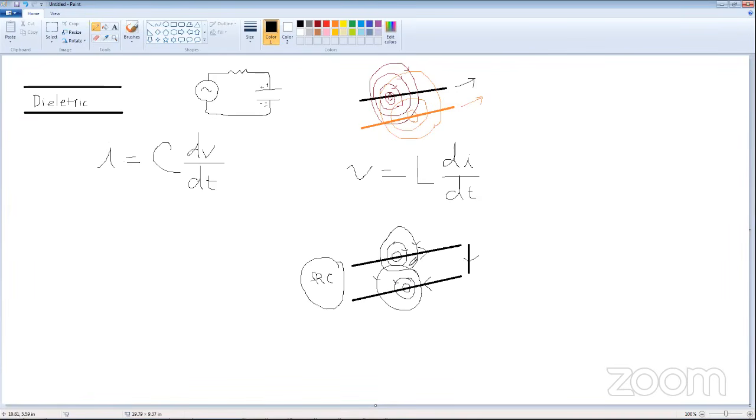So they end up canceling, minimizing their impedance. What this means is that on a PCB, even if you have a huge ground plane, the return current is going to try to follow the signal current as closely as it can, because in doing so it's going through the minimum impedance path. And it's because they end up canceling out their mutual inductance.